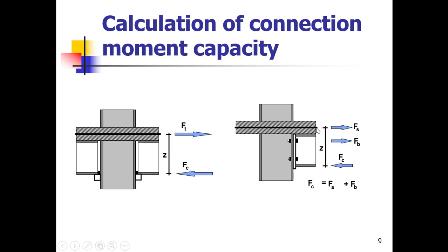Here, this is the force expected to be taken by the reinforcing steel and the group of bolts. What happens under the bending of the beam is that this bolt group is subject to a tension-compression system. Suppose under the application of moment the neutral axis falls here. In that case, some of the bolts are in compression, some of them are in tension. In addition to the reinforcing steel, the total system is subject to a tension-compression system, so that will resist the applied moment.